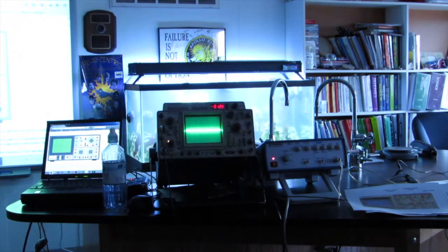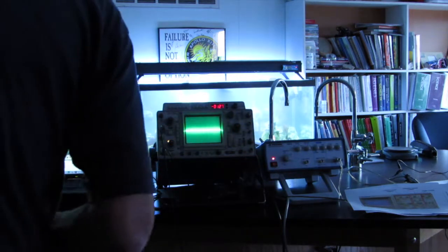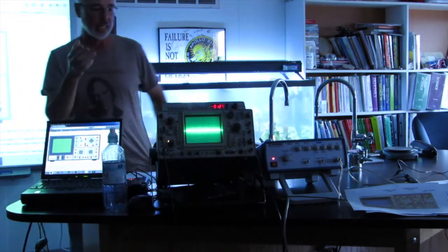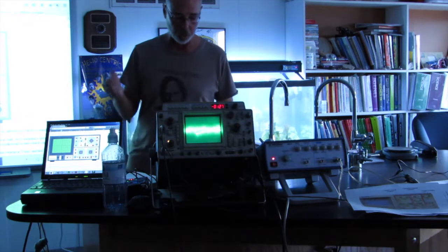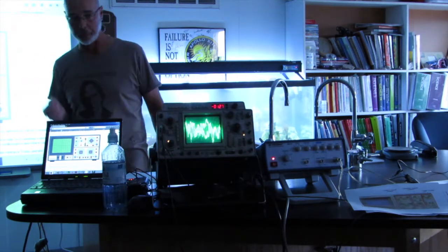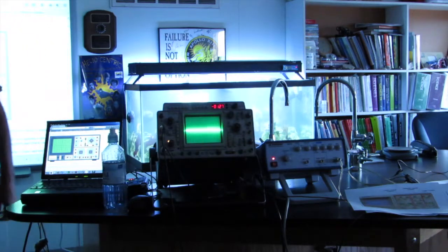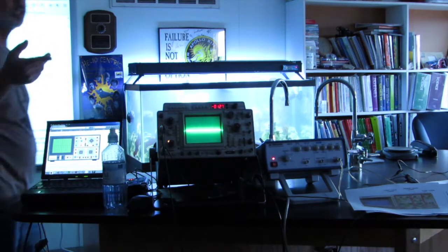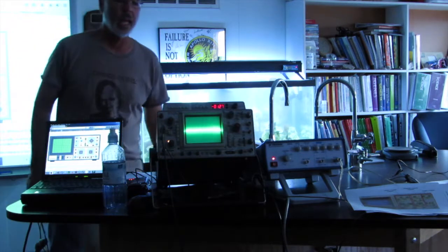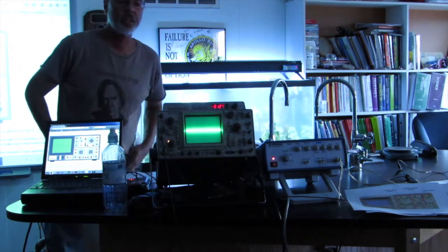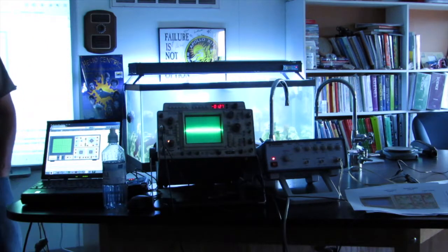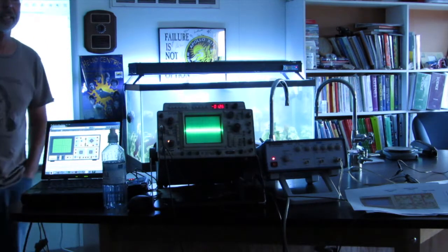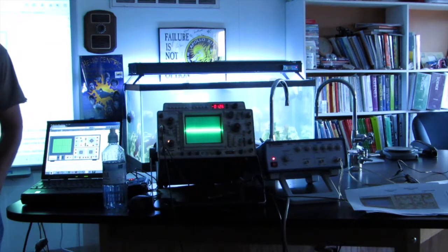Now I'm free running this right now. I have the trigger set to auto, as opposed to normal, where it waits for a trigger. Auto will wait for a trigger for a little bit of time, but then sweep anyway. That's just so you can always see a display, even if you have no voltage. So if you would just speak into that. Notice that the softer passages are lower in amplitude, but if you go "ha, ha, ha," then you'll see that the amplitude increases.